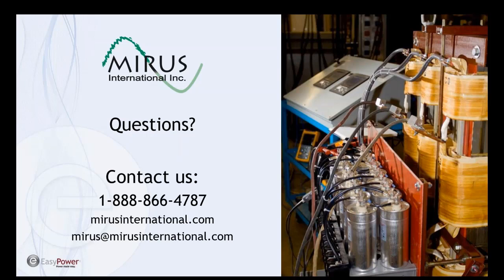I guess I didn't refer to it in this particular webinar, but TDD is a term that was created for IEEE 519, and TDD is defined as the total harmonic distortion, or THD, times the ratio of the actual fundamental current measured divided by the peak demand fundamental current.